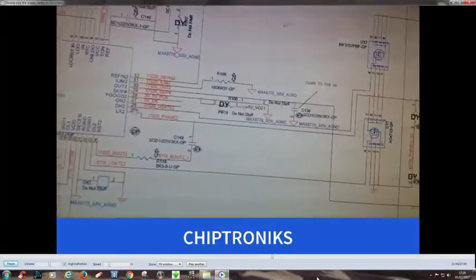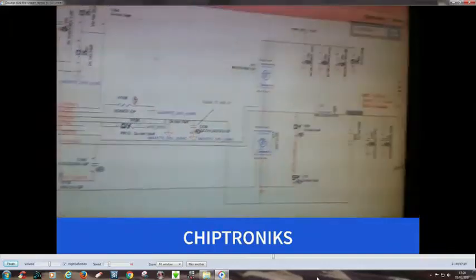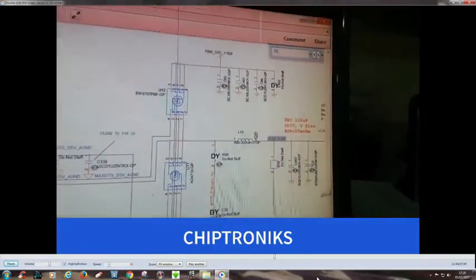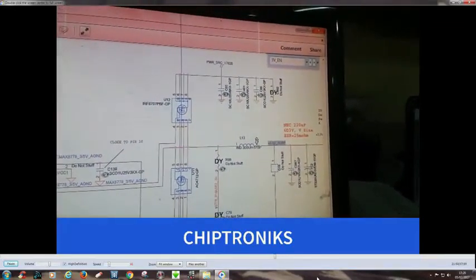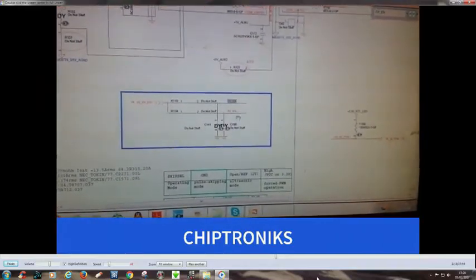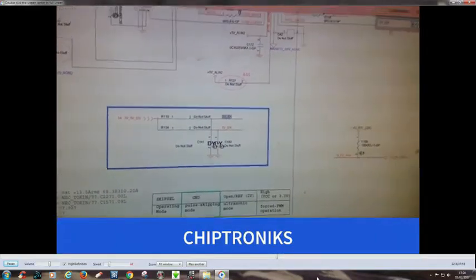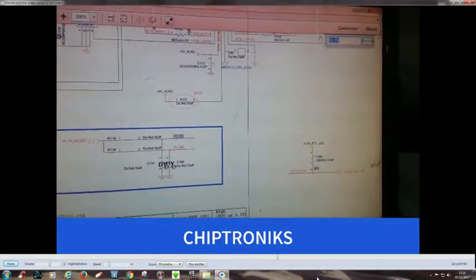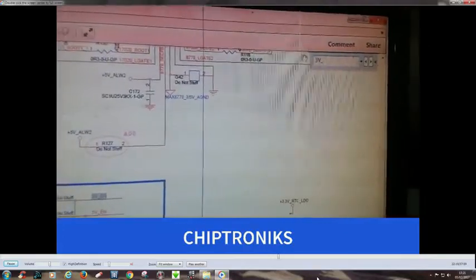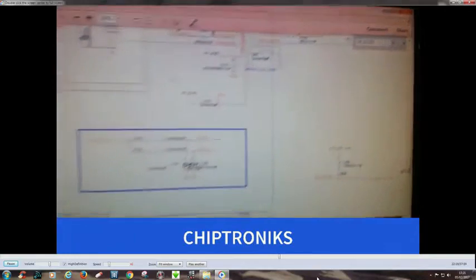and this regulator will generate the driving voltage once it receives the enable signal, and you can see this is 3V underscore EN, that is the enable signal. So let's find from where this 3V underscore EN is coming, and you can see this 3V underscore EN is coming from 3V underscore 5V underscore EN. Let's find out from where this 3V 5V underscore EN is coming.